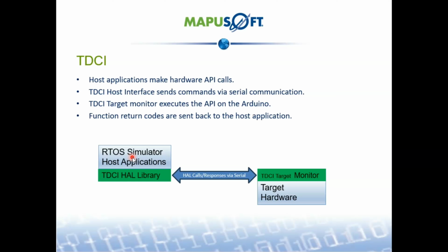The microcontroller converts the analog input to a temperature value and compares it against the predefined safe limit that we already set as the threshold value. If the temperature exceeds the threshold, the microcontroller activates an indication to signal that overheating is happening.